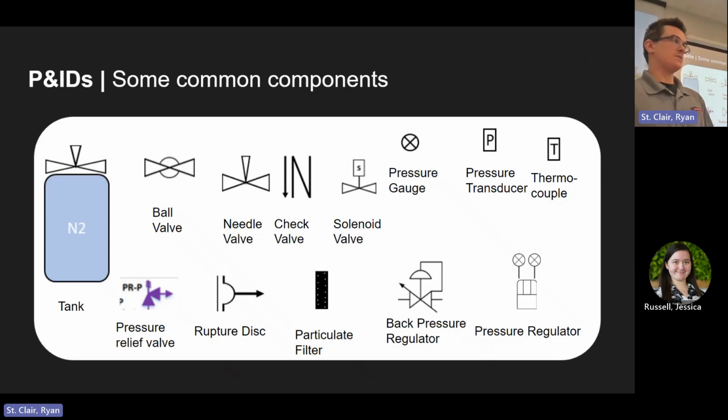We included one in our design because we thought better safe than sorry. Physically it wouldn't make sense to have a fuel line produce pressure if it were to combust upstream, because there's no oxygen present, that fire triangle idea. And can a check valve even react fast enough to prevent a hard start like that? Say there was fuel and oxidizer in one line theoretically, could that prevent that combustion from going backwards? And people say no.